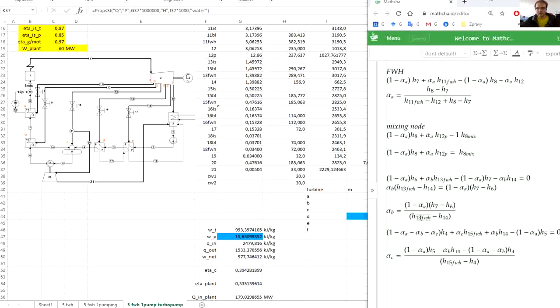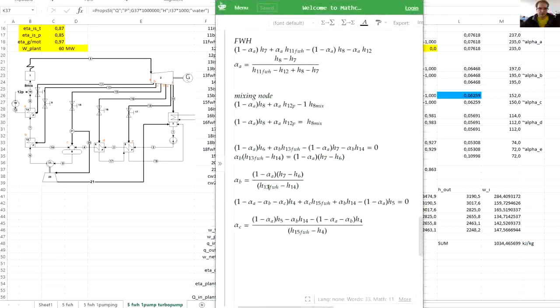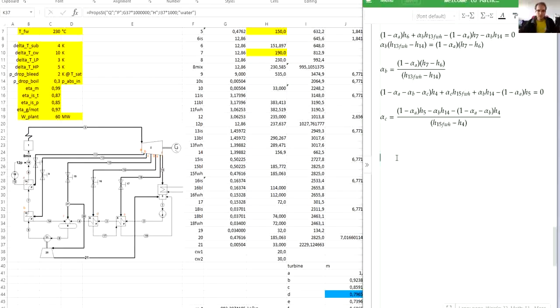So we go into our equation editor. So the isentropic work of the turbopump turbine, so let's put it as work turbopump turbine isentropic, multiplied by the mechanical efficiency of the components, or basically of the bearings of the turbine. So times eta m, as eta mechanical.